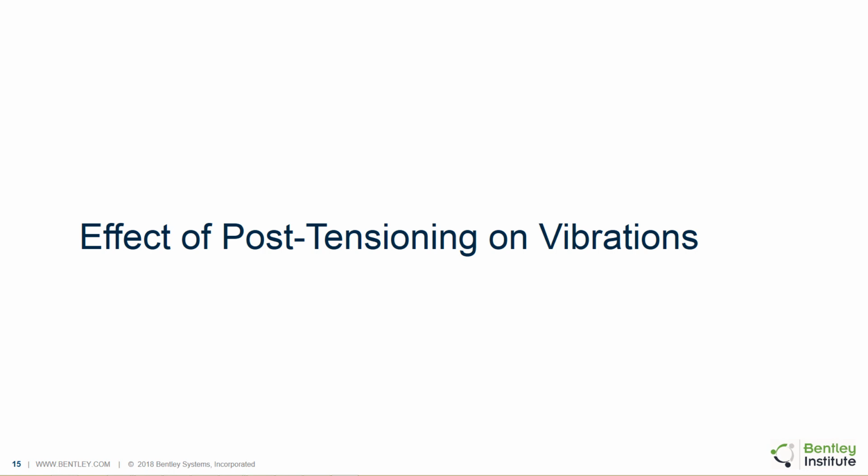With that said, there's some other research I've read that indicates and talks about a behavior called compression softening due to post-tensioning, which would be analogous to buckling. So the frequencies would be reduced as the post-tensioning is increased to some large level due to a buckling effect. And so in that scenario, the post-tensioning could have a negative effect on vibrations. It could actually reduce the stiffness instead of increasing it. So I'll leave the decision as to whether or not to include cracks up to you.